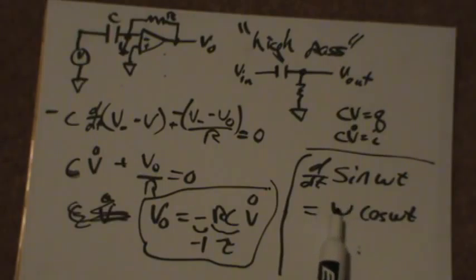If omega is really small, that'll be multiplying by a small number. So in essence, low frequency ones, the amplitude gets driven down, so they get killed off. High frequency ones will be amplified, i.e. high frequency lives. So this is a high pass filter. So differentiation becomes a high pass filter.